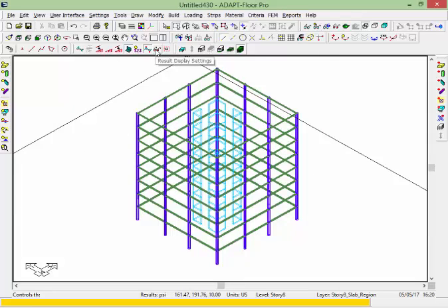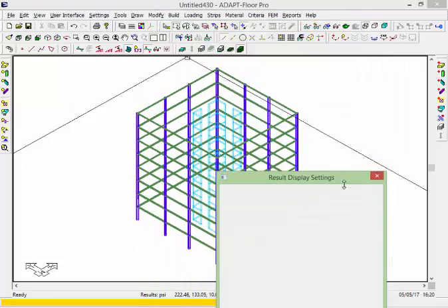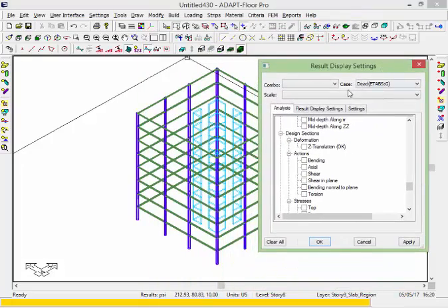If I turn on the result display settings inside of Builder, you can see that for the load case options we have load case results, and those results are all ETABS results. So for dead, EQX, EQY, live, modal, WindX, WindY, we have the tag ETABS, meaning the results stem from that program and they stem from a global analysis in ETABS.